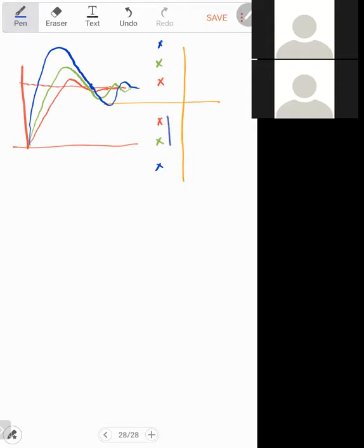If you move the poles along this side, remember that the poles will be symmetrical. This line will be symmetrical in the S plane. Both poles will be symmetrical above and below the real axis. So this is the pole motion. If the real axis is fixed and the vertical axis is variable, then if you increase the vertical axis, the overshoot will increase. So remember that one.